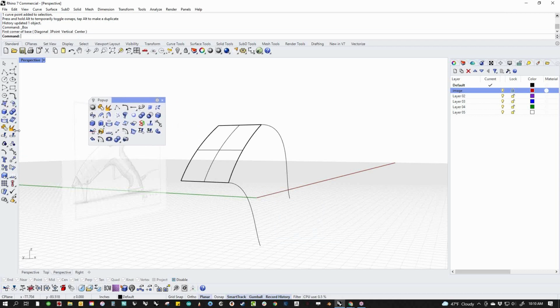And then what you can do is come over here and hold down the control key, not the shift key. If you hold down shift, see how it says move edit? If I move this out of here, it's actually going to remove it from this toolbar, which I don't want to do. So I'm going to copy it, and I'm just going to drag it over here and let it go. And that allows me to put it in there. Now, if I want to remove something from here, because this is a copy, I can do this. Now I can hold down shift, pull it out, and it just deletes out of that.